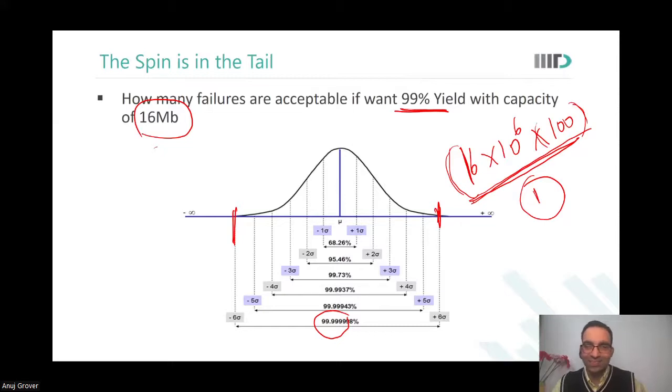So you're saying that even in one die, if one bit cell fails, my whole die will fail. But I would have designed it such that if some bit cells fail, other bit cells can take their place. We've not talked about it yet. For present understanding, if even one cell fails, the die is rejected.